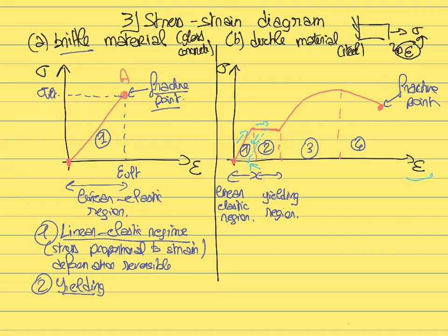You apply a given stress to the material, it becomes deformed, and then you remove this stress and the material remains permanently deformed. If we draw what it would look like, you would increase the stress like this. At some point you would enter the yielding domain, and after you unload, the material remains permanently deformed.